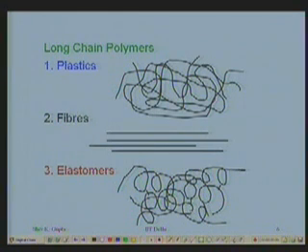So it is between the two. If I do the cross linking at all places, then it will be absolutely a network polymer. But it's only a few places where these cross links are there, and the chains are quite coiled, not really zigzag. These materials, when they are stretched, stretch 300%, 400% of their original length, and when you release the force, they come back to their original shape and size.